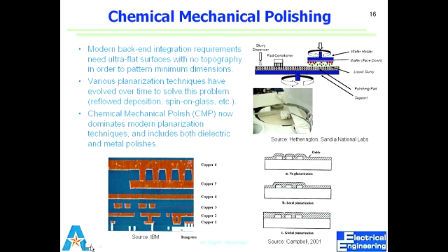So it depends on if we are concerned in planarizing just in a small region, or if you want to do planarization over the whole region. And essentially, if you break the process down simply, there's this holder which is keeping the wafer face down and it's rotating, and then we have this polishing pad which is also rotating.